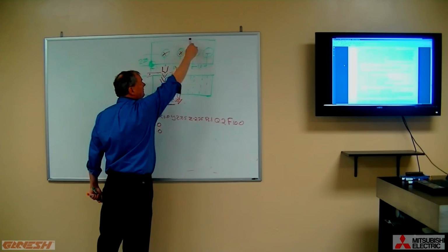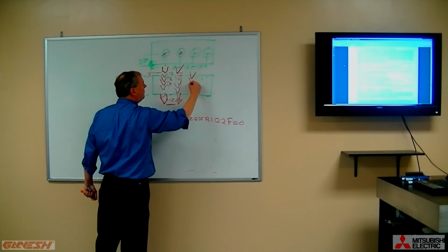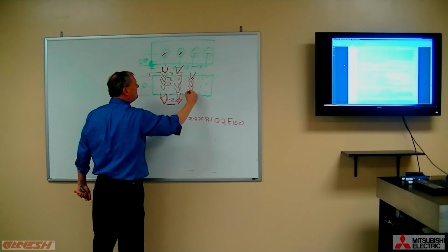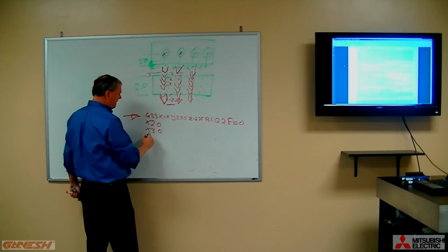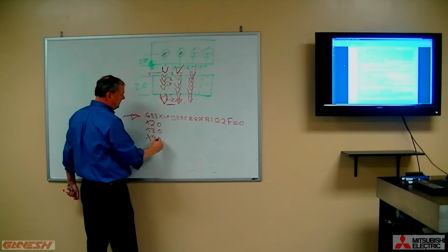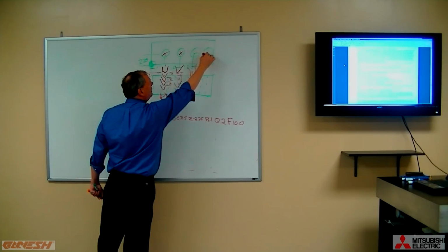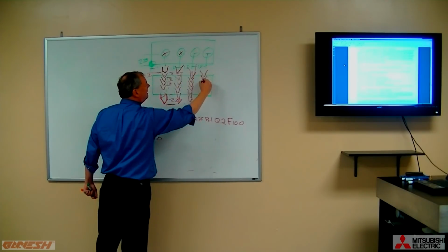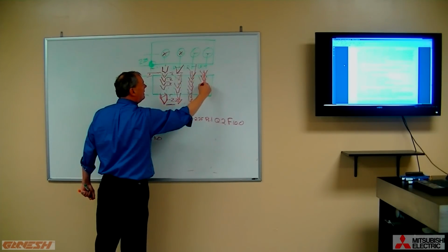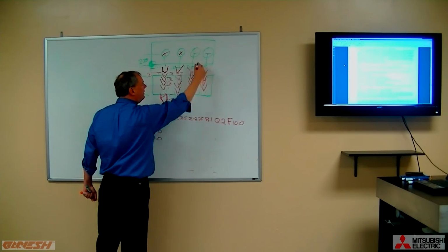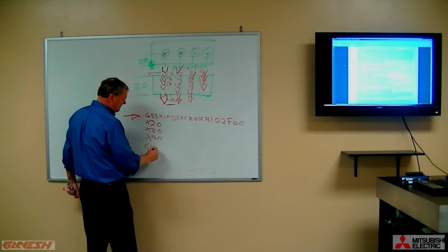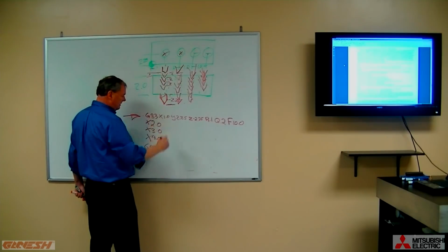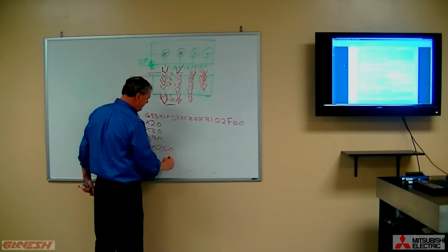Now it's going to position over and it's going to do your 200 thousandths of a step each time. Wrap it back out, wait there for some instruction, and we're going to say X 4.0. Going to move over to our last hole. Start pecking, down, out, down, out, down, out. And then all you do is you say G80, give it some Z value, Z 5.0 or whatever, and you're done.